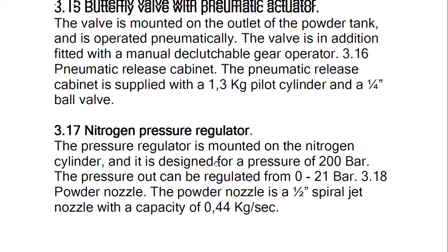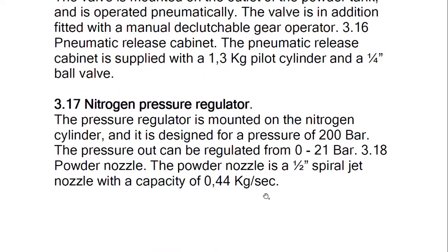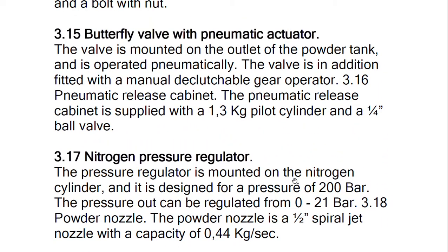Okay, so this was all about the components of the fixed firefighting installation, that is DCP. On tankers you will find it. We have discussed today about all the mountings, what is the tank construction of a nitrogen tank, or there are two separate tanks for the nitrogen and for the storage of the powder, how the system is working, what are the mountings on the tanks, how it is operating, and at what pressure nitrogen gas is used, what is the component of the powder, and we also discussed about the portable fire extinguisher and what is there in the cartridge, how the cartridge works and how the DCP comes out. We have discussed everything in detail.